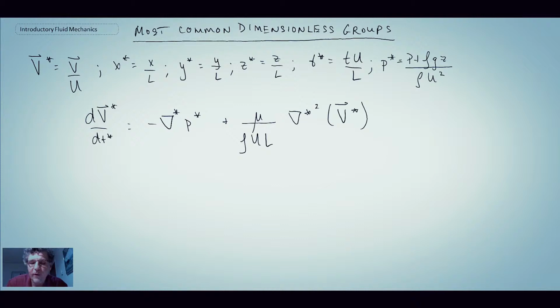So we've transformed the Navier-Stokes equations into this new equation, but what we notice is that we have this pre-multiplier term here, and it's 1 over a very common non-dimensional number in fluid mechanics, the Reynolds number. So by going through this process, this gives another example that there are other ways that we can get these non-dimensional parameters that are very important within fluid mechanics.